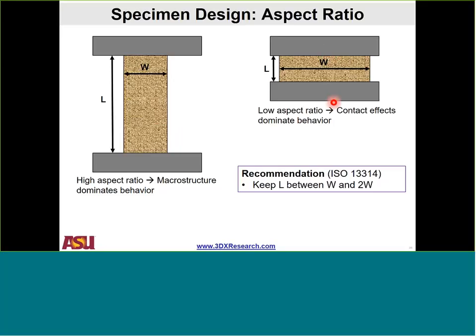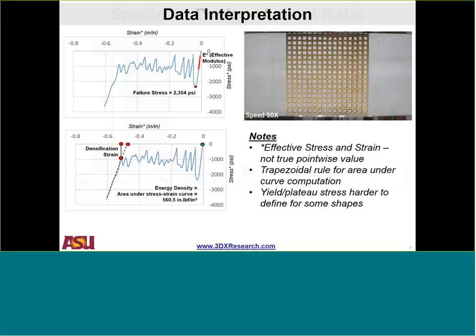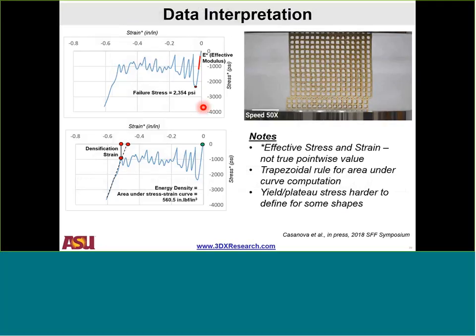So the contact effects could dominate the behavior. The ISO standard recommends keeping the height between 1 and 2 times the width, and I have no reason to disagree with that. So that's worked for us as well, so that's a good thing to keep in mind. Finally, two more things to talk about. One is the data interpretation.